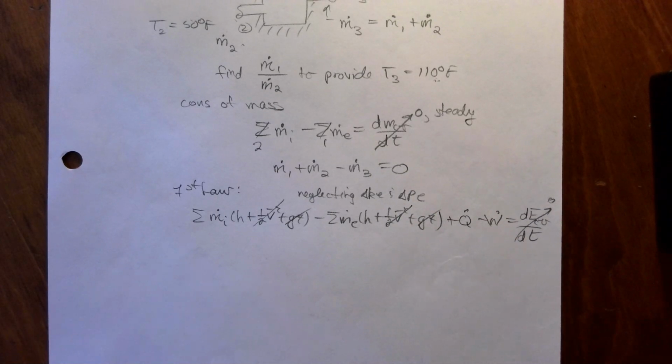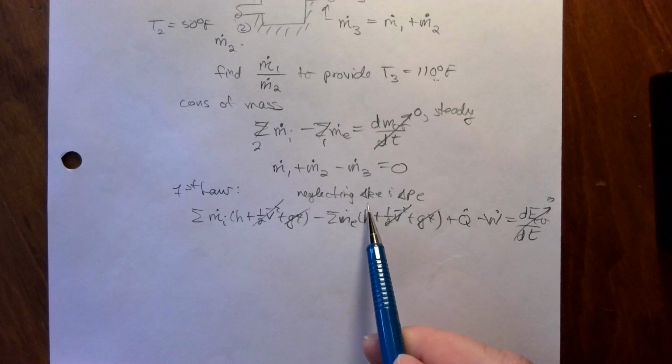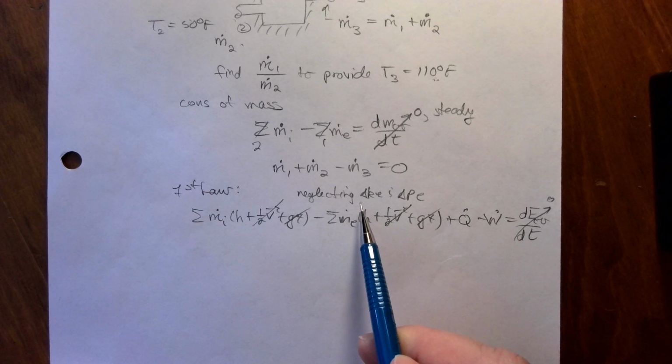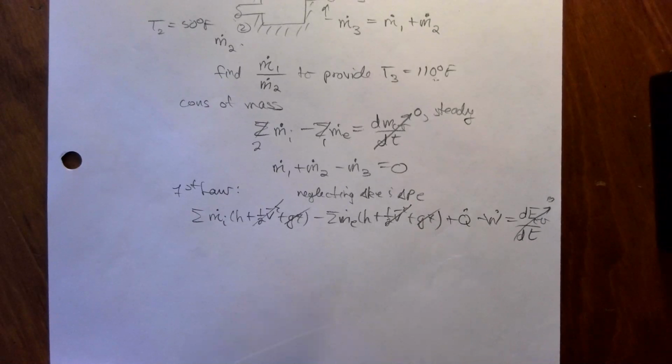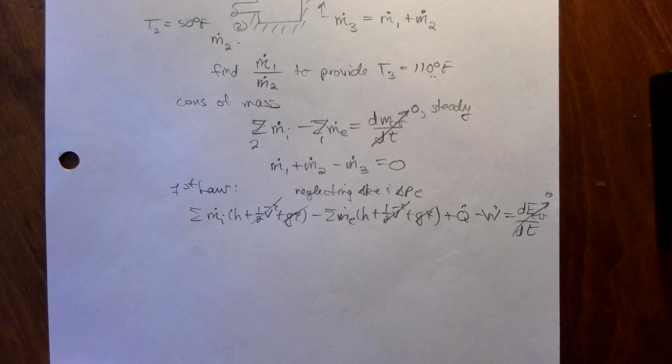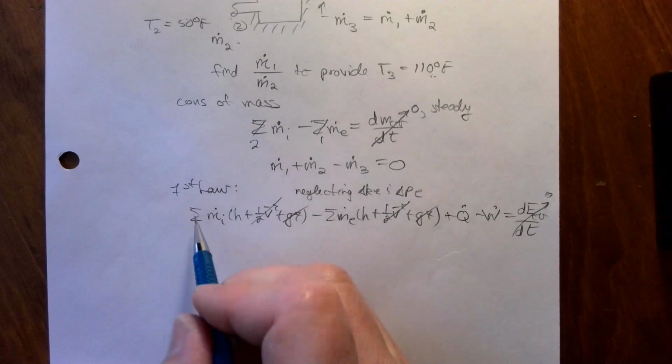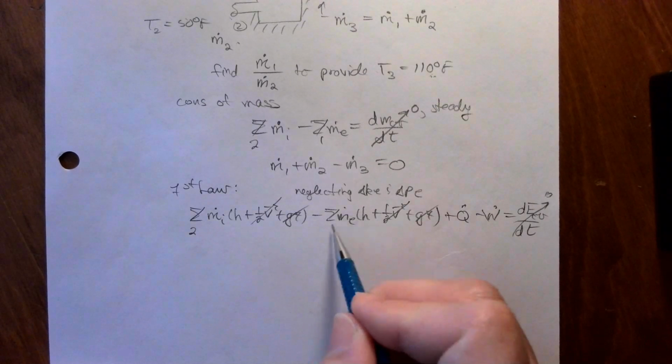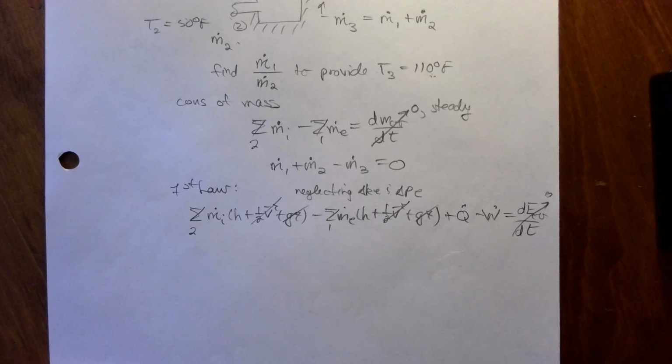We're not given information about the cross-sectional areas or velocities anywhere, so we couldn't include that if we wanted to. That will likely be negligible for this device. This is not intended to be a nozzle or diffuser. Potential energy is effectively always negligible for these small devices. At the end there's two inlets again, and one exit.